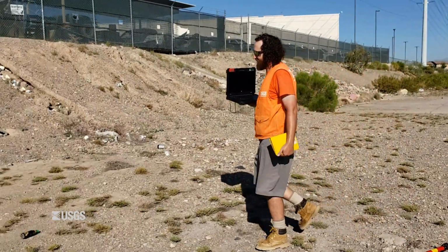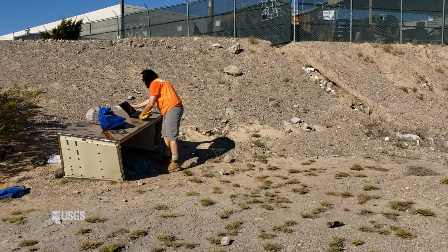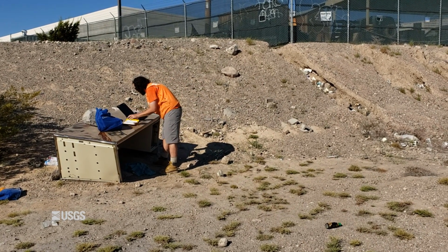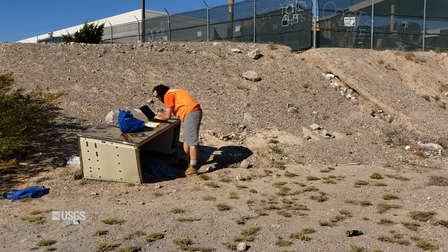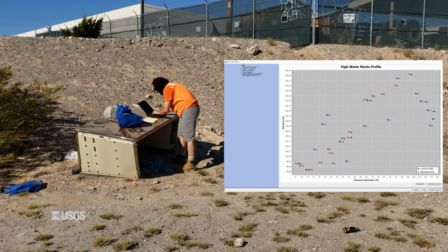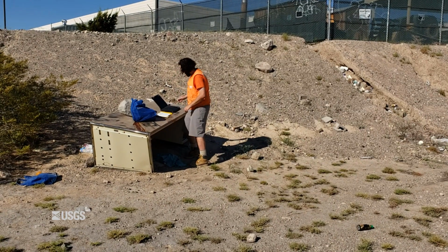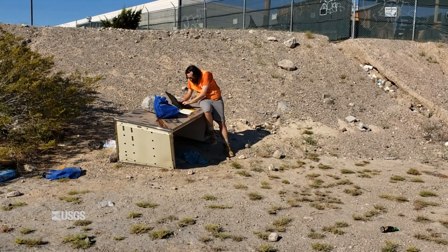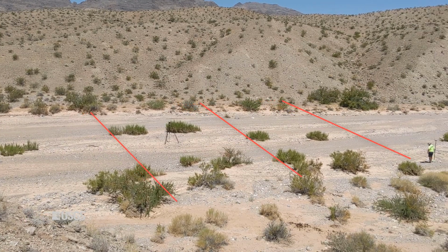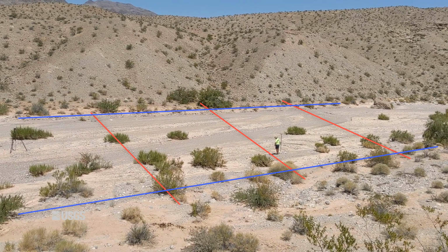We are required to plot our high water marks in the field to identify significant breaks in the water surface profile. Remember that whole discussion about steady, uniform flow and gradually varied flow concept I covered in the theory video? Putting our cross-sections at major breaks in the water surface profile will allow us to approximate steady, uniform flow through the entire surveyed reach. Additional cross-sections can be placed in more uniform parts of the reach as appropriate, so we have an adequate number of cross-sections in the study reach. We will need at least 3 cross-sections for a slope area measurement. Placing your cross-sections correctly will result in a more reliable measurement using the slope area method.